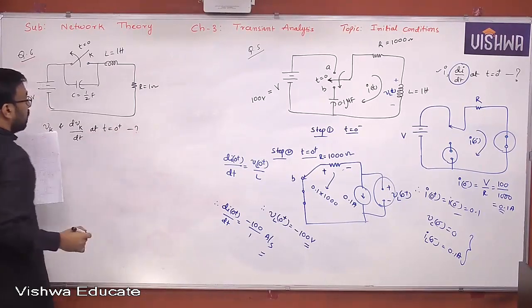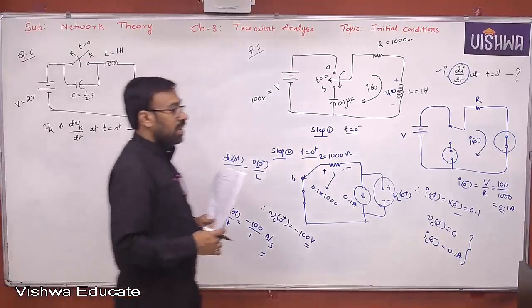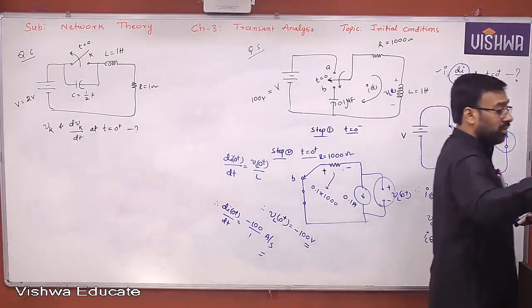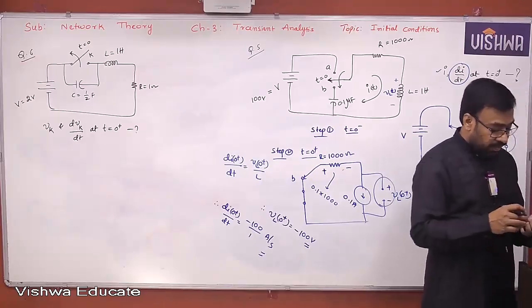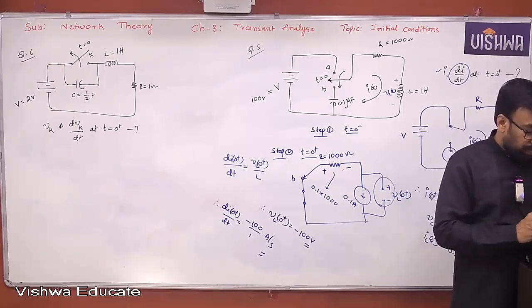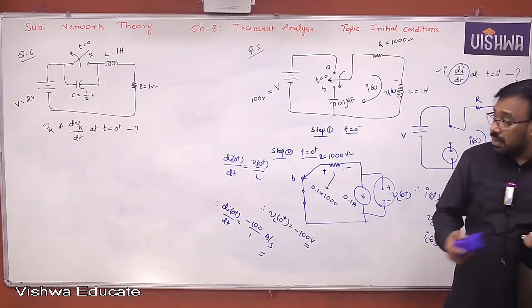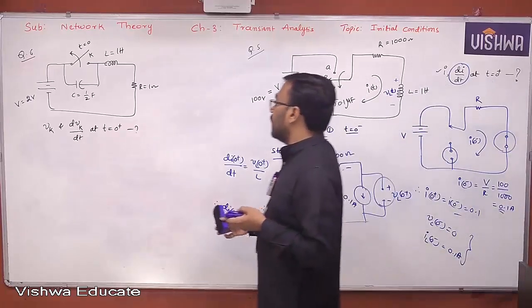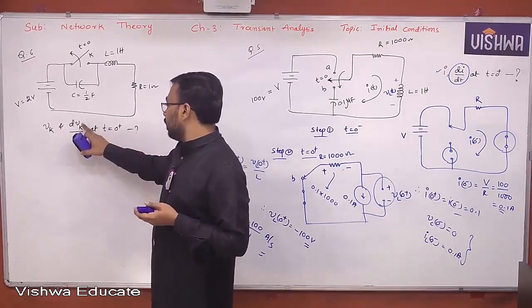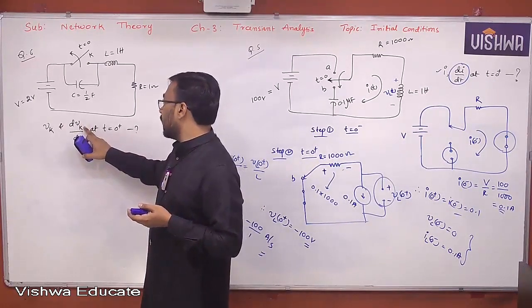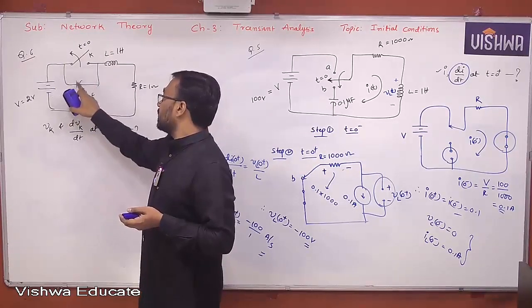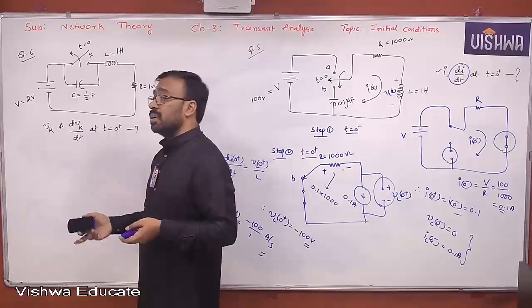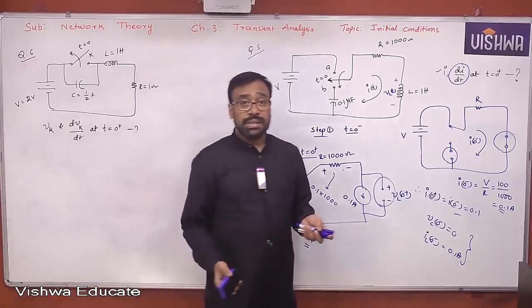Okay. Now again the derivative term. Whenever there is a derivative term, usually it will be first order. But anyway, you have to check once. And first order derivative terms are given in the problem. Then you check whether that voltage Vk, in dVk, is the voltage across the capacitor or not. Vk is nothing but the voltage across the switch, but the capacitor is also placed across the switch. Therefore, it is the voltage across the capacitor.